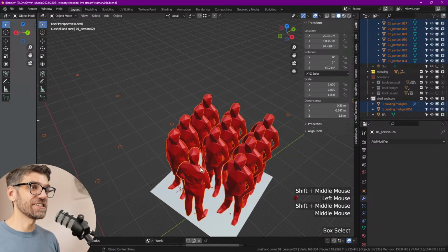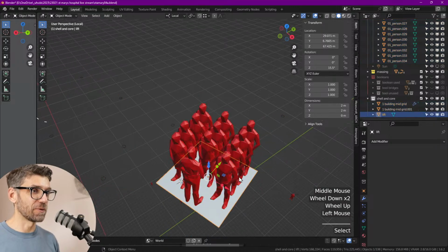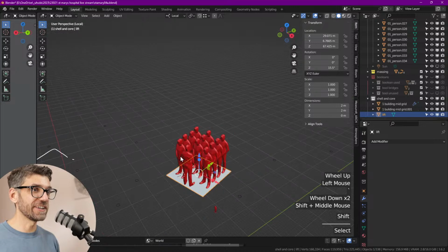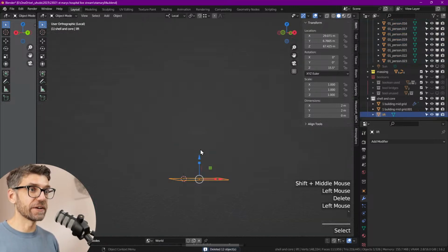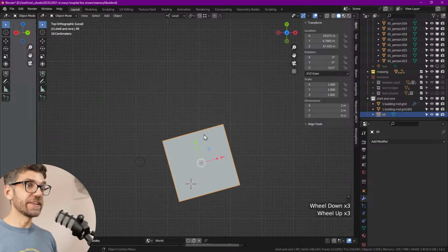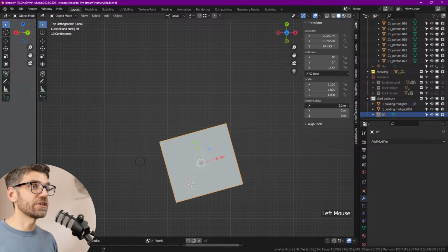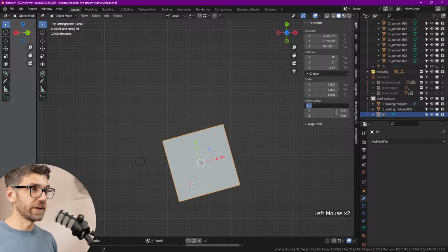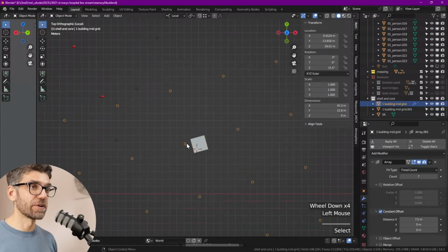that lift size is pretty good. That's what I'm trying to say. We can fit quite a few people. You'll be surprised how many people you can fit in a 2x2. Of course, if you have a wheelchair, which is something that happens often, that takes the space of 4 standing people. So maybe in one direction, we make it a little bit wider. And usually we also figure out the structure, which we have over here, based on our core size.